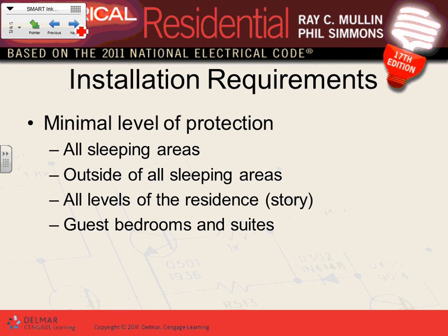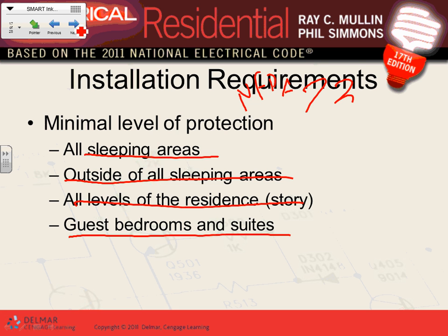Now, here's where you guys are gonna wake up. Where do I need smoke detectors? Smoke, not heat. Smoke detectors in a dwelling, based on NFPA 72. You need them in all sleeping areas, outside the sleeping areas, all levels of the residence, and guest rooms, bedrooms, and suites, like hotels and motels.